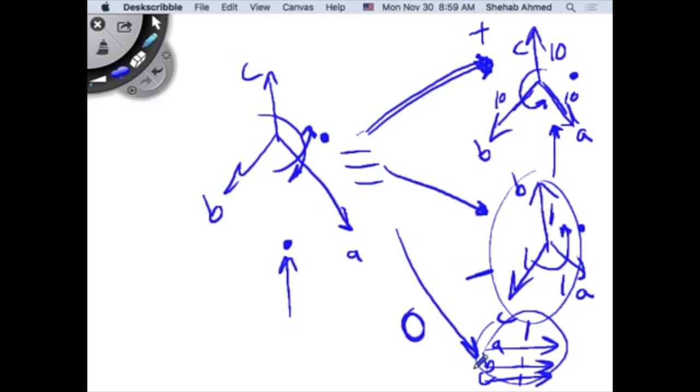So if I have three voltages that are in phase with each other and I apply them to a three-phase system, they're not balanced. I mean, they're not a balanced three-phase, 120 degrees apart anymore. If they're all in phase, the currents that they generate will also be in phase, right? These are three-phase voltages applied to these three resistors. These are all in phase, not 120 degrees apart.